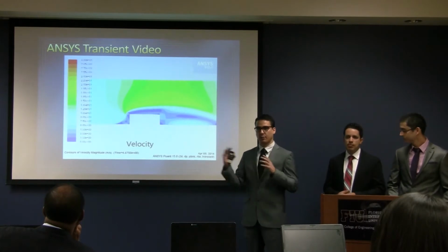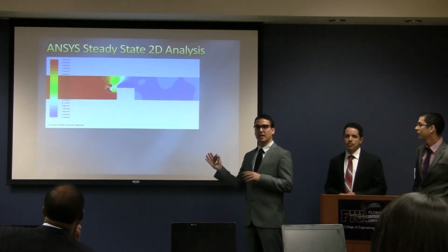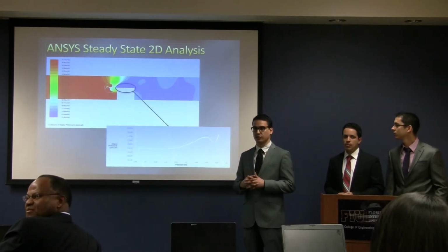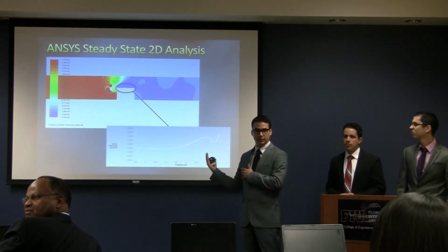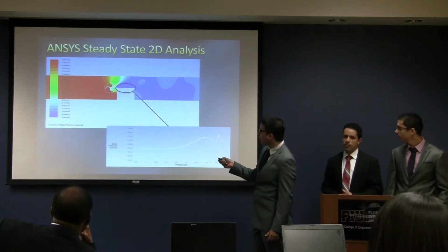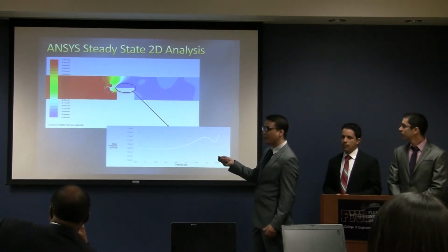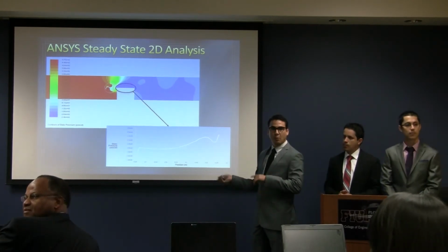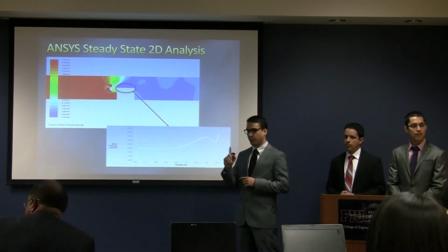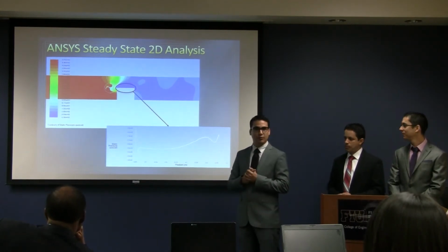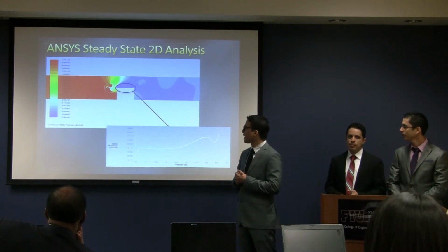Transient gives us a progression, and we use it mainly so everyone can understand the type of analysis we were running with ANSYS. It gives the pressure profile on the roof, which we then extract in the form of a graph and plot together with the pressure points that we measured in the lab, creating the comparison graphs you are going to see on the next slide.